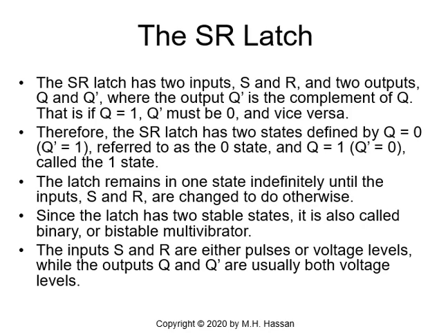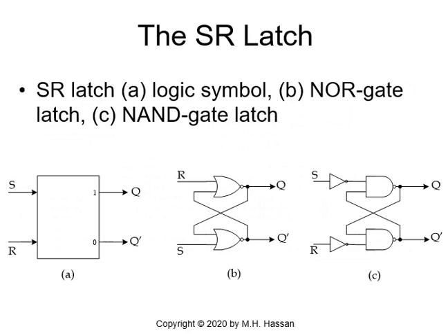Now the next slide will show us the block diagram of the SR latch and its logic symbol, where we see the inputs S and R and the outputs Q and Q prime. Those are the latch designed with 2 NOR gates and with 2 NAND gates and inverters. They are cross-coupled NOR gates, where the reset is on the top, applied to the upper NOR gate, and the set is applied to the lower NOR gate.